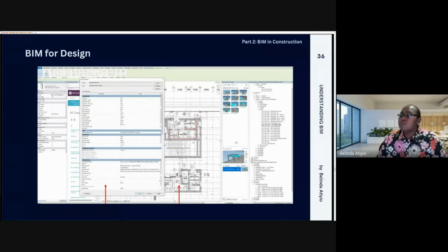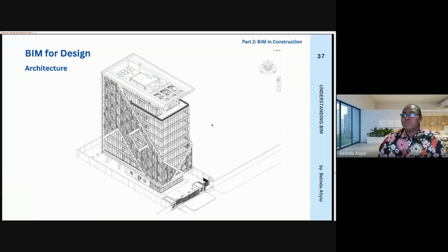Now, on this side I have some plugins for BIM Collab. So while I'm drawing, I'm also doing some clash detection, and it's automatically saving the pictures where these issues are. If you click on it, it will take you to that part of the model. Those are the kind of things that make your work easier. In fact, when we went to site on this project, we had almost no issue with documentation. You know, like you get to site and you see a column where you never planned to see it before. That didn't happen here, because even before going to site, we had already done all this. We had already seen all the issues that were going to come up.